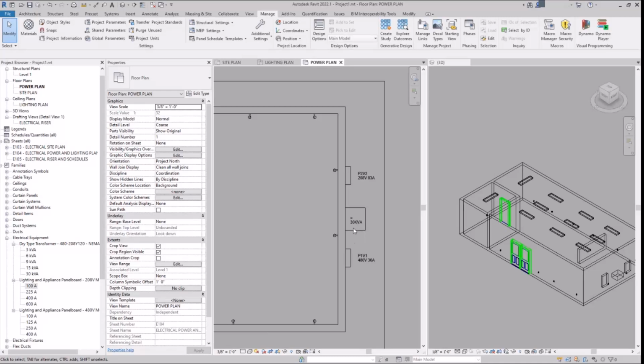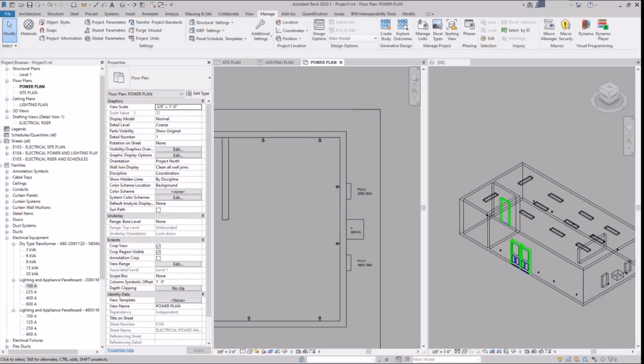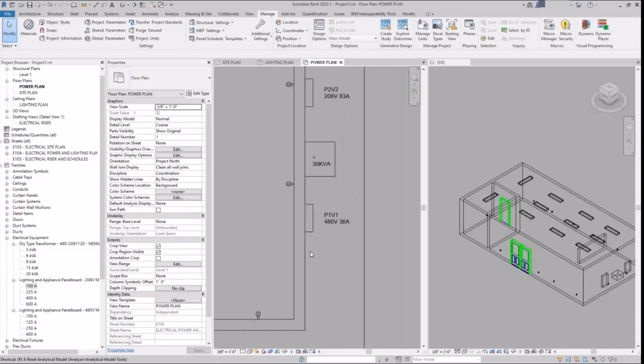Because if there's only one thing that you're feeding from the 480 volt transformer before you start feeding 208, 120 stuff, that's all you need, just a disconnect. There's only one thing. You don't need a panel board to feed multiple things. Gotcha. And yes, that does occasionally happen, by the way. So you do a disconnect on the transformer? So it would be a service disconnect. Mm-hmm. I'll just draw it right here.